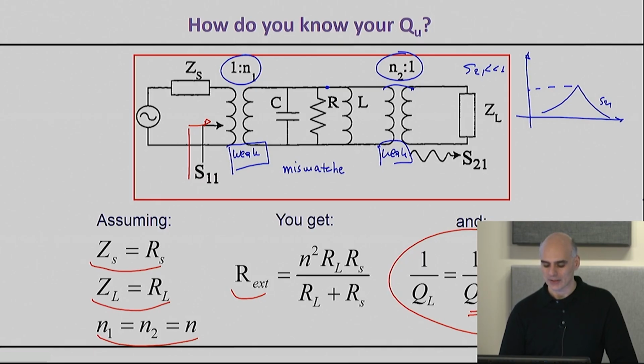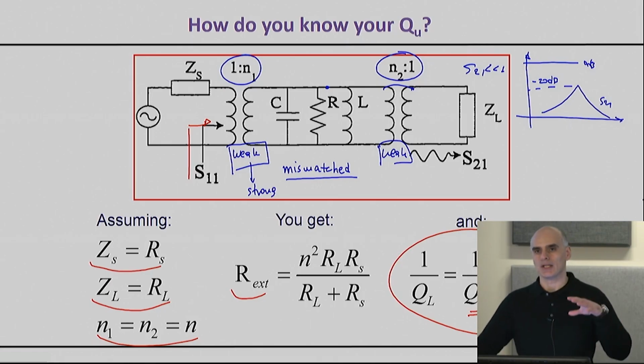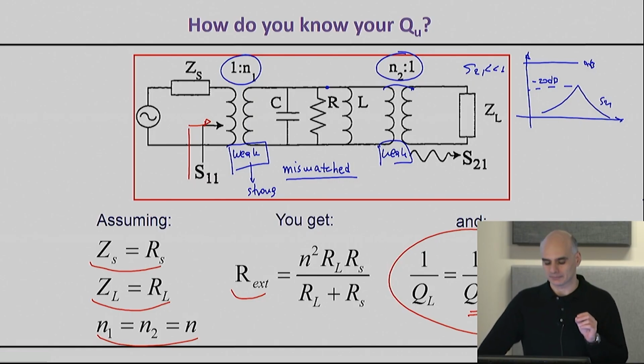And so when you make a measurement here, your S21 will appear that low. But that's not because the resonator is bad, that's because you purposely designed this to have a weakly coupled section. Or if you want to say it in different words, you have purposely mismatched the filter. So the loss that you see here, so again, this may be the 0 dB line, and you may be down to the negative 20 dB line, that loss that you see is not ohmic loss, it's just mismatch loss. And you can fix that quite easily when you make the real filter by simply matching the circuit, by simply fixing the coupling from weak to strong, which is something that will happen when you do the filter. But once again, when you measure the resonator, you barely tap it.